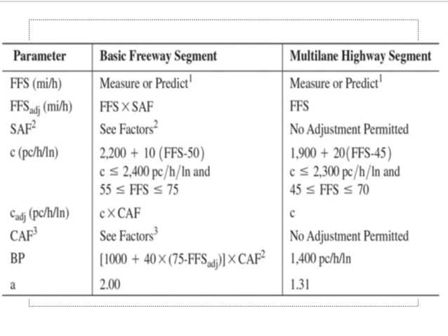Clear? Now what if the equation gives you here 2400? Then what do I do? For multilane highway, I use the equation, I get answer 2400. And this says it should be 2300 or less. What should I do? We already calculated. Now the answer is more than this. What should I do? I take 2300. So the equation only works up to here. After this is the value.